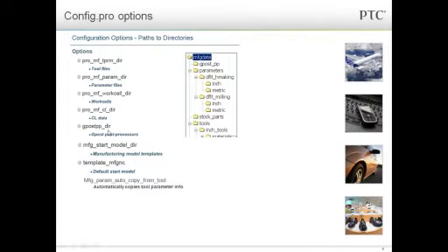Your post-processor directory, for those of you that are using the software now and you don't have this set, essentially when you go to post-process a file, you get a list of about 20 different post-processors that you have to navigate through. If you put your post-processors in a specific folder and have this option set, instead of seeing all 20 of the posts that you'd have, you'd only see the ones that you actually used.